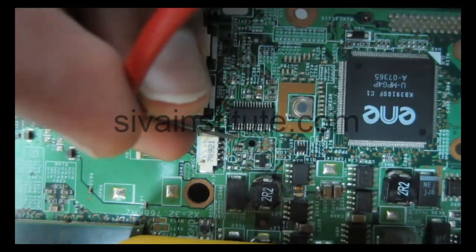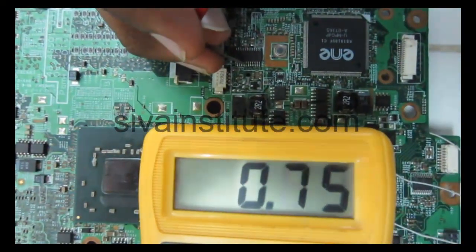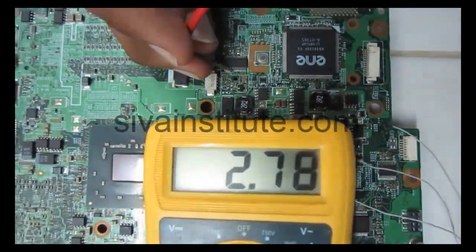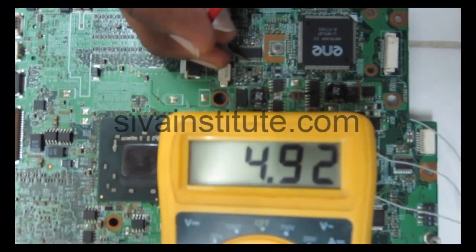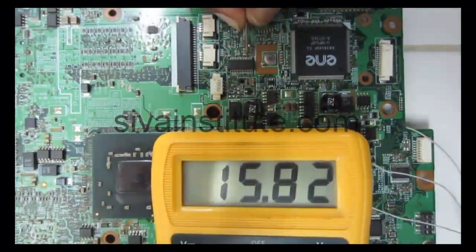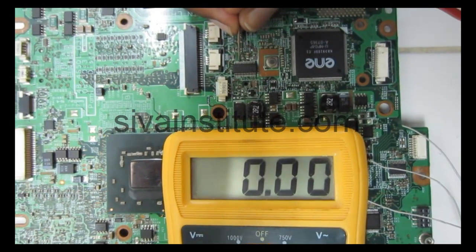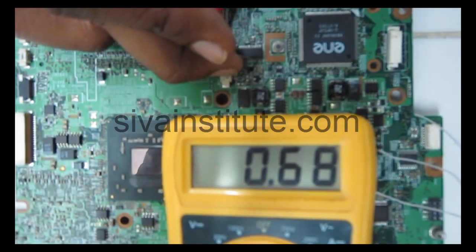We will see here without the S4 command: pin number 21, 4.95 volts, okay. Pin number 22, 4.9 volts. This voltage is also okay. Pin number 4, 15 volts adapter voltage. Pin number 11, 0 volts. Pin number 26, 0 volts.